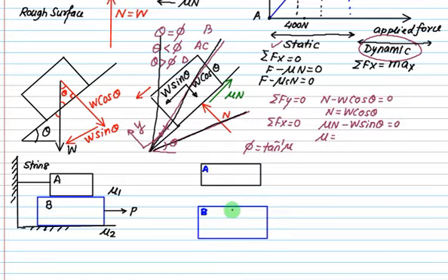How are you going to start this? First of all, let's show the force W1 or WB. Then show the normal reaction NB. Then show the weight WA. This body will push this body, so the weight will act downward, and you get a normal reaction like this.